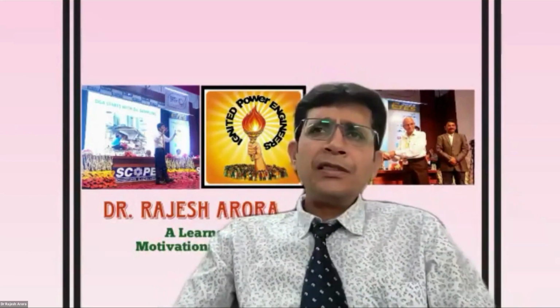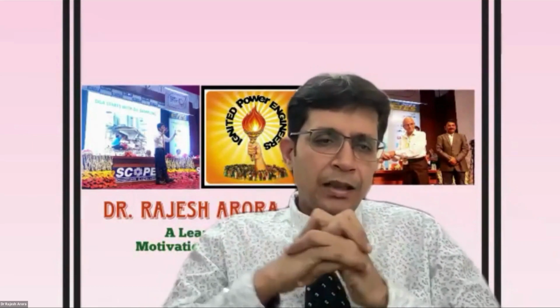Sir, one more question is there from JPDCL, Mr. R.K. Gupta. Transformer absorbs moisture. What is the rate of absorption? This, I think, is a question which relates to how the moisture enters. Yeah, I can tell you one thing. Everything depends on the relative saturation, and that is temperature dependent. And that depends on the load of the transformer you have.